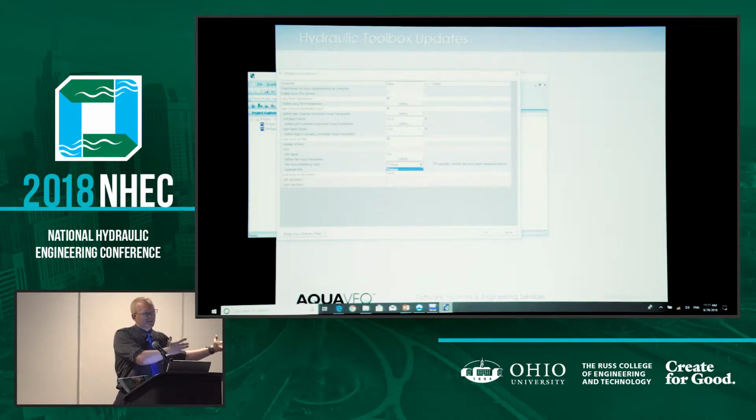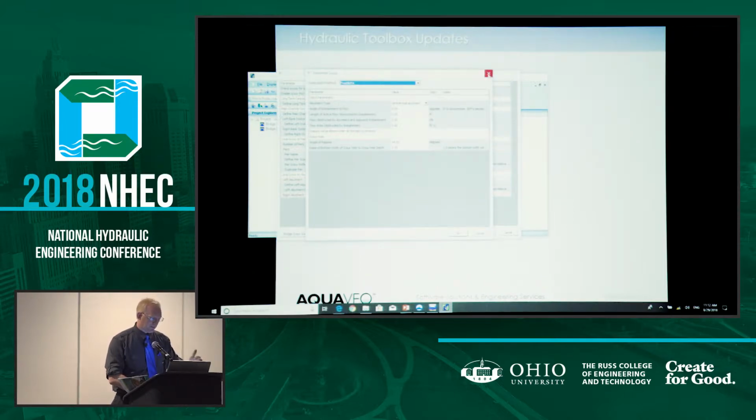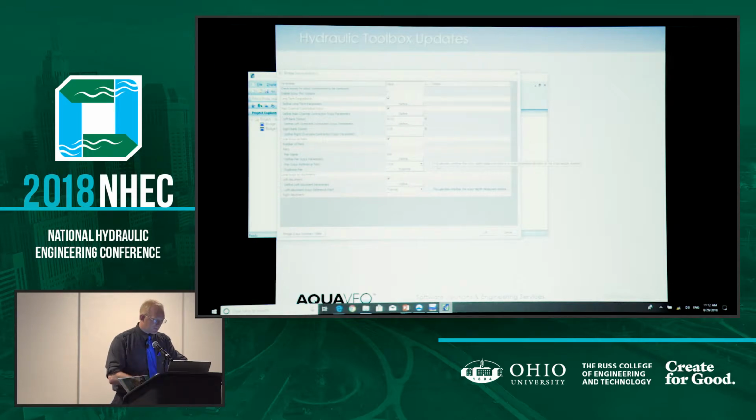But maybe you're clear up on the overbank and you know that channel's not going to move over there. In that case, you can select a local scour depth, and it will just start at where the pier meets the stream bed. And then we have a left abutment, and pretty similar. We have the ability to define our options and choose our reference point.